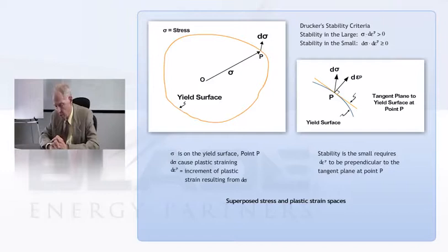Now, there's some materials that just don't fit into that. For example, if you take something like a sand or a soil that compacts. If you've ever noticed this, when you take things that crumble, they start to break up in areas all over the place. They don't shear uniformly when you apply a shear stress.